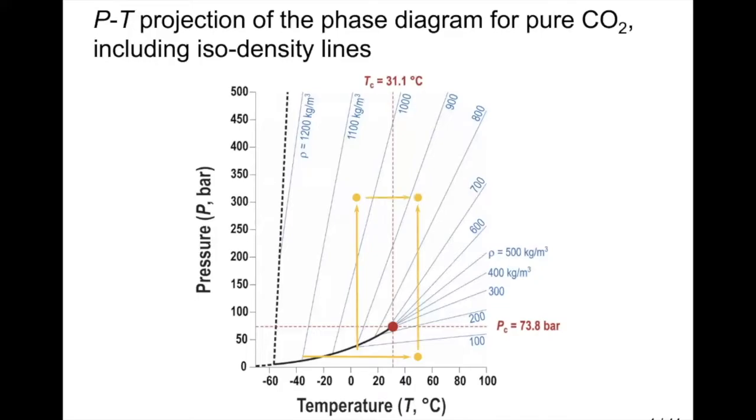Above the critical point, heating and compressing allow reaching the same conditions, but without the phase transition. These temperature changes result in the same change in density at a near critical pressure at 100 bar and typical extraction pressure of 400 bar. This change is small near the critical point where CO2 is highly compressible, but larger at high pressure when CO2 exhibits liquid-like properties.